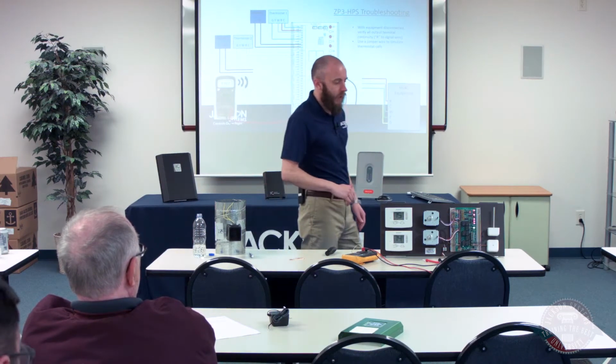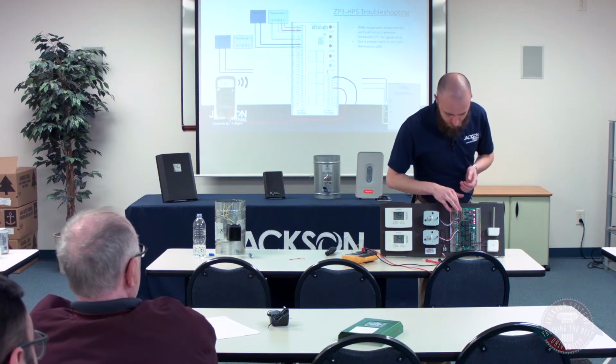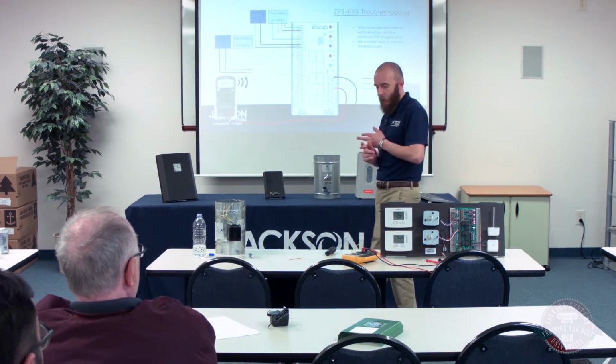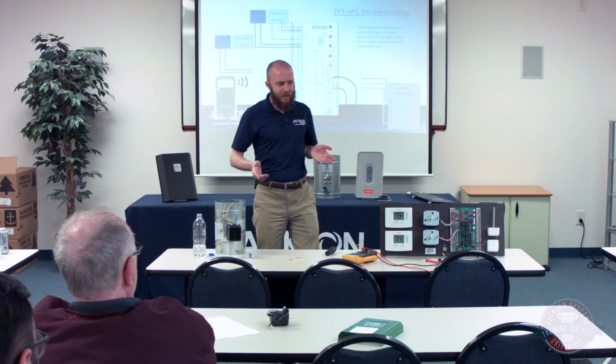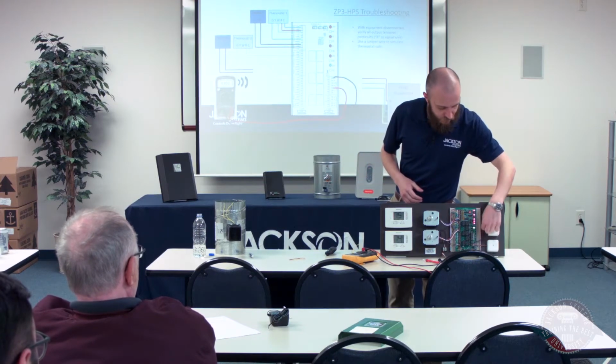But that's how you're going to check your outputs. So continuity to check your outputs, voltage to check your thermostat inputs, voltage to check your damper outputs. And then the last thing to check sometimes that comes into play is if you need to check your sensors.